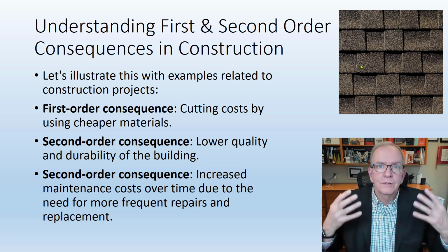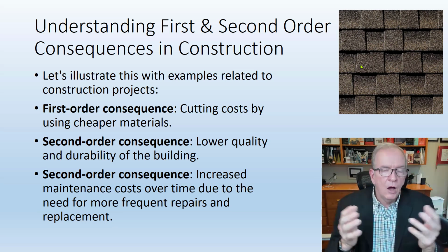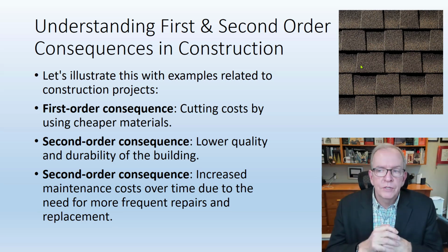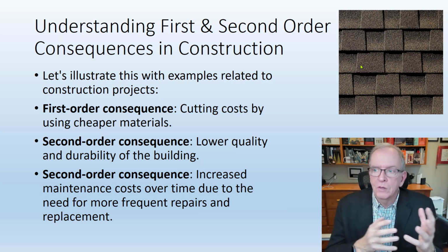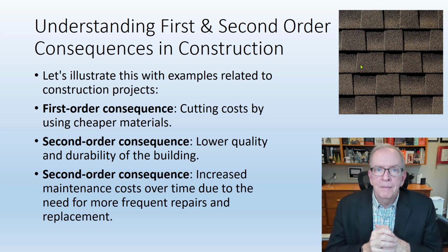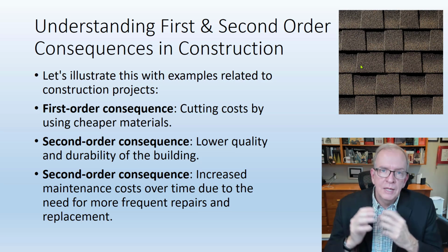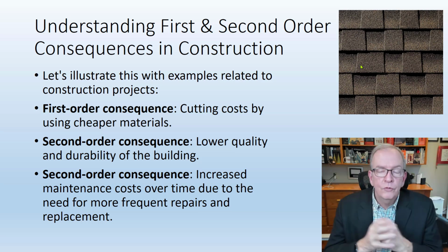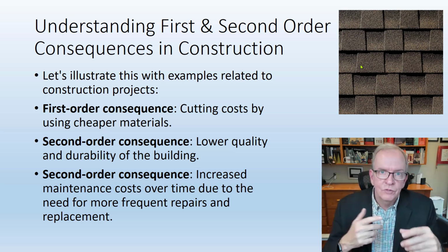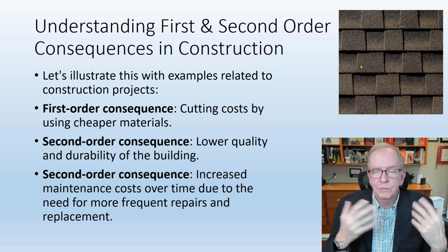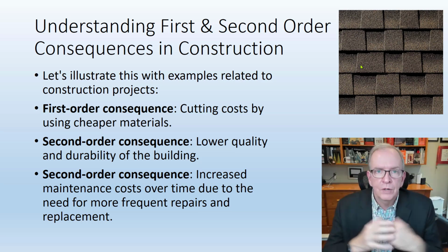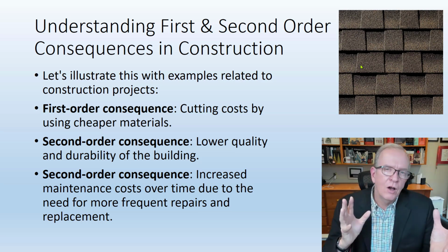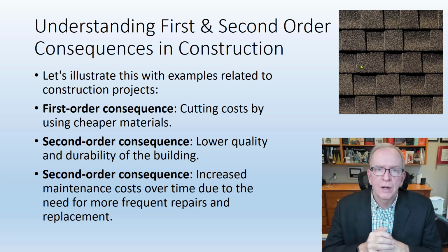But if you're a building or facility manager, say for an office building or a college or university building, and this is going to be a long-term building, then it might make a lot more sense to go with a more expensive type of roofing membrane, probably flat roofs in those cases, right? Because the extra cost of changing it in 12 years, especially if you're talking flat roofs, 12, 14 years, can be quite substantial. So there's the life cycle cost of what this particular product is, but it's also thinking of the second order consequence.